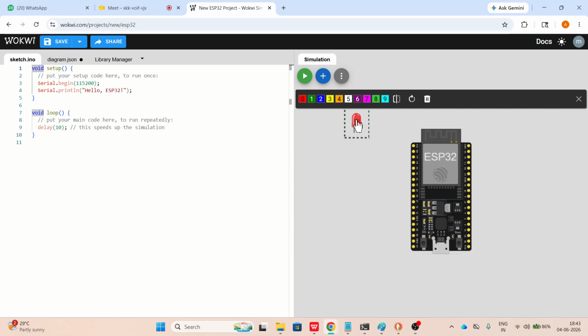You can connect it to any digital I/O pins of the ESP32. The ESP32 has many digital I/O pins. It also supports I2C and SPI protocols, and it has built-in Wi-Fi. Since it has built-in Wi-Fi, you can push the data from the ESP32 directly to any of the MQTT brokers.